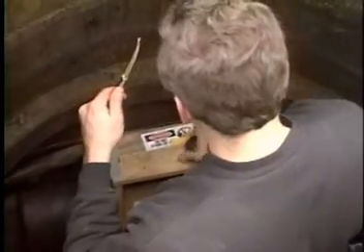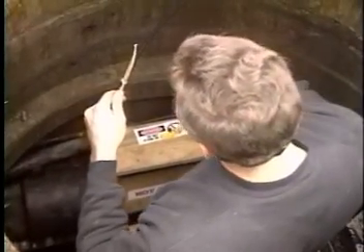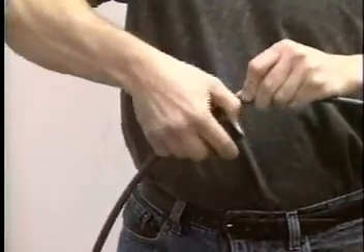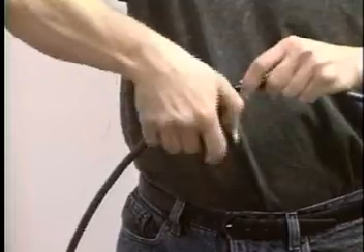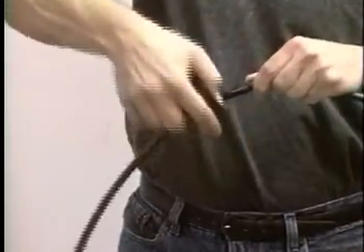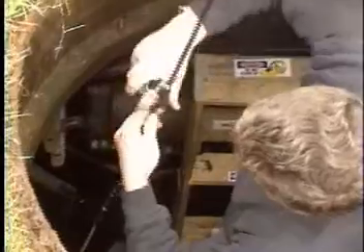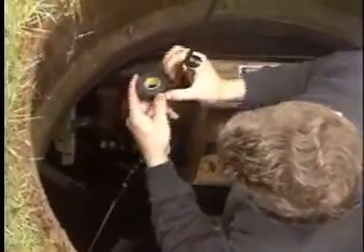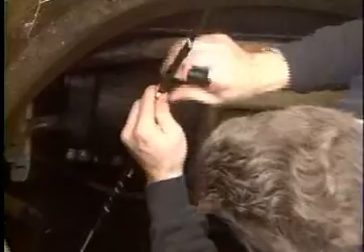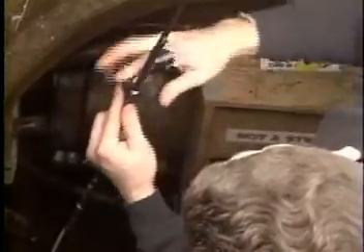When pulling a very small diameter cable through short runs, the cable itself may be tied to the pulling line and covered with electrical tape to prevent the joint from hanging up along the span. The electrical tape is applied from the cable end towards the pulling line so the tape edges overlap like fish scales. This prevents the tape edges from snagging during the pull. The tape also seals the cable ends, preventing fiber damage and contamination by dust or moisture. During any cable installation procedure, care must be taken to properly seal the cable ends.